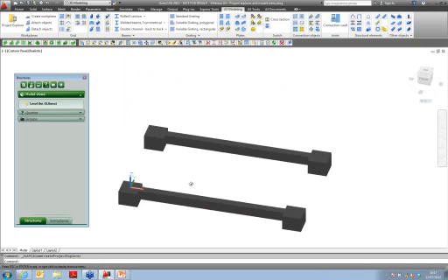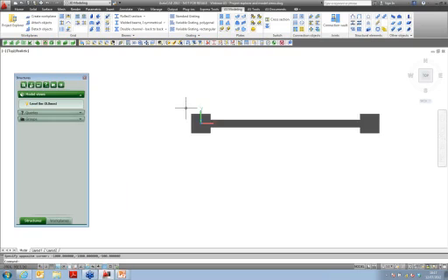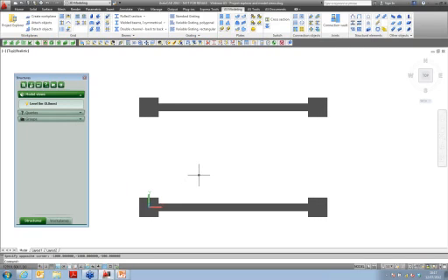It's easy to rotate like that. If you double click here on this line, you have a top view which is created on this level. So now it's easy to work on level 0 and to complete my foundation. In Advanced Steel, of course, we can create steel structures, but you have also some easy to use tools to create concrete elements. So I can, for example, create a beam from this foundation to this one.